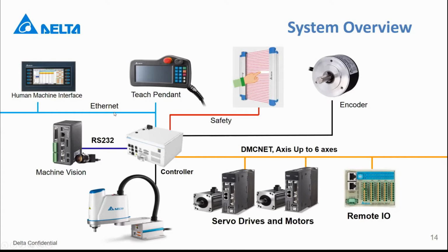Both of them are based on Modbus. So for 232, we have Modbus RTU, and for Ethernet, we have Modbus TCP. But for now, we're also working on other Ethernet protocols like OPC UA and EtherNet/IP. And we will support these two protocols soon.